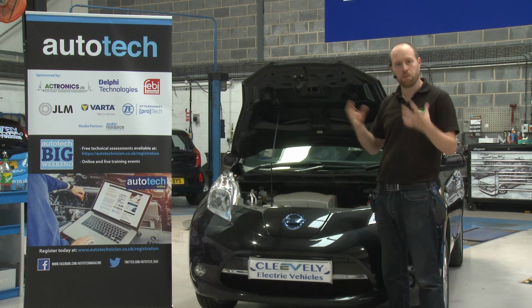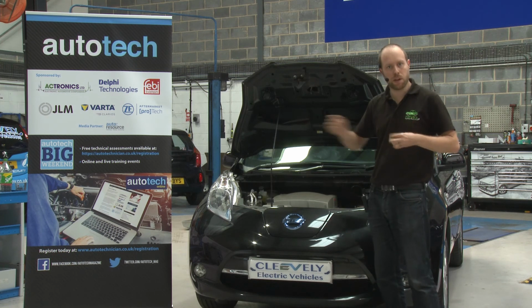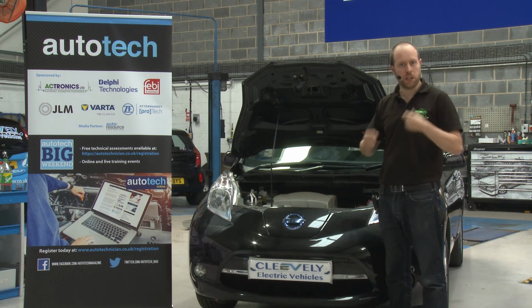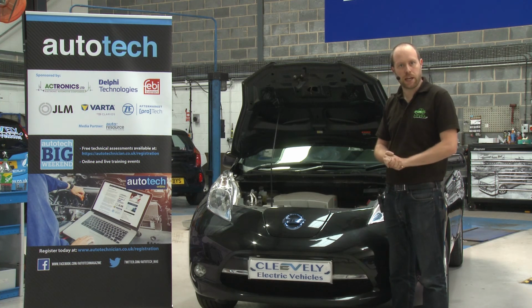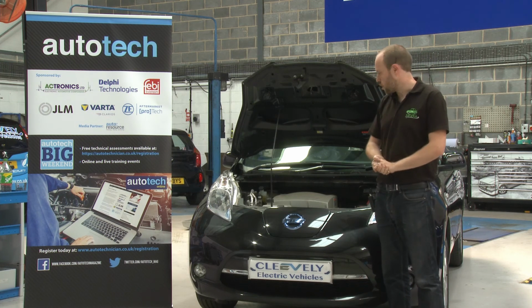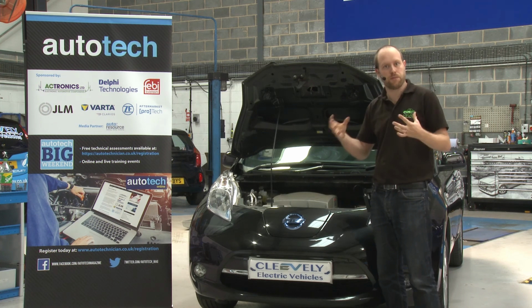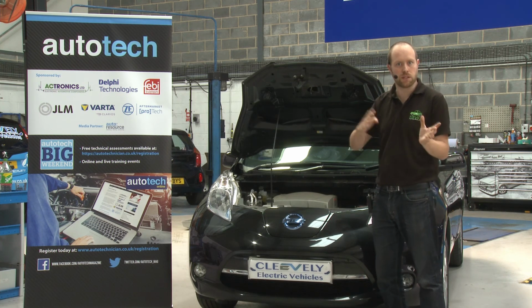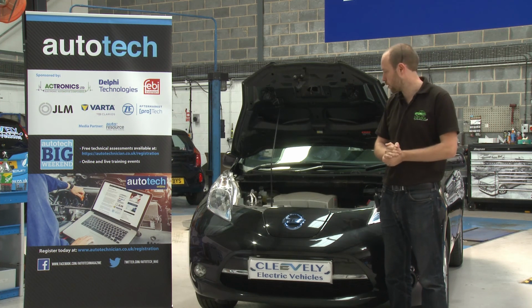So if we get a problem with this, when we've got the heater on, we can end up accidentally cooling the cabin, or when we've got the air conditioning on, we can end up accidentally heating the cabin if we've got a problem with one of those valves. So the way we check those valves is by using something like an infrared thermometer or a thermal imaging camera. We can see where the hot parts of the circuit are, where the cool parts of the circuit are, and referring to the diagram, we can see if those valves are in the correct position. If we then suspect a fault with the valve, we can look at the electrical control of the valve and see whether it's receiving the right signal to get it to the right position, so whether it's a fault with the valve or a fault with the electrical supply to it.